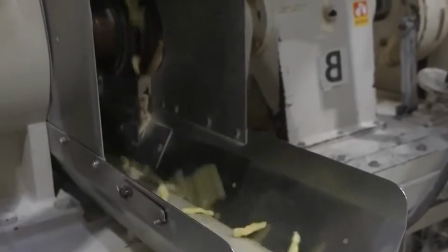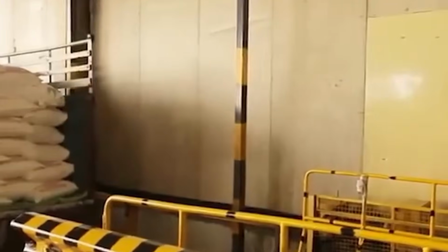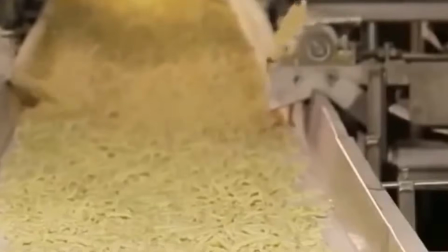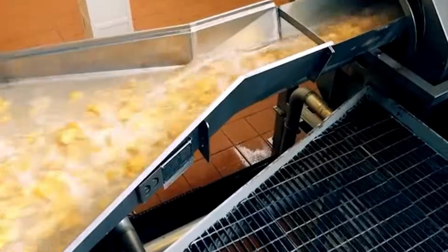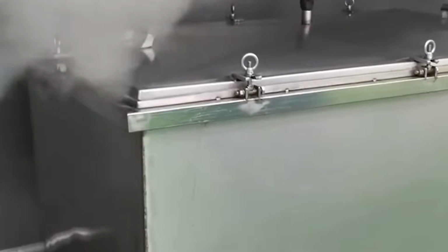application system. Oil-based or water-based slurries are sprayed through atomizing nozzles onto the surface of the snacks as they rotate inside the drum. The seasoning adheres to the surface oil or residual moisture, forming a uniform coating. The slurry composition includes cheese powder, salt, flavor enhancers, colorants, and anti-caking agents. Slurry viscosity is controlled through inline viscometers, and pump speed is adjusted accordingly.